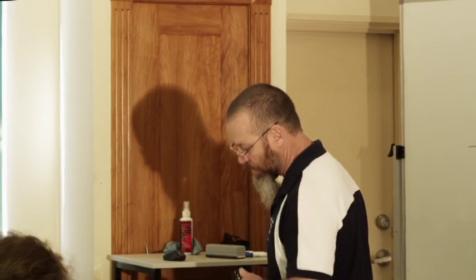When you find out it's a nominal connection, you go to table 9.4 on the opposite page. And what you'll see with table 9.4, it's actually broken up into 3 different areas. One is floor framing, one is wall framing, and when you go over the page is roof framing. So if you wanted to connect your top plate, a rafter top plate, obviously that's a roof framing connection, you just go to the roof framing section on page 170 or 168, depending on your book. You see there where it says rafters to plates or ring beams, coupled roofs.